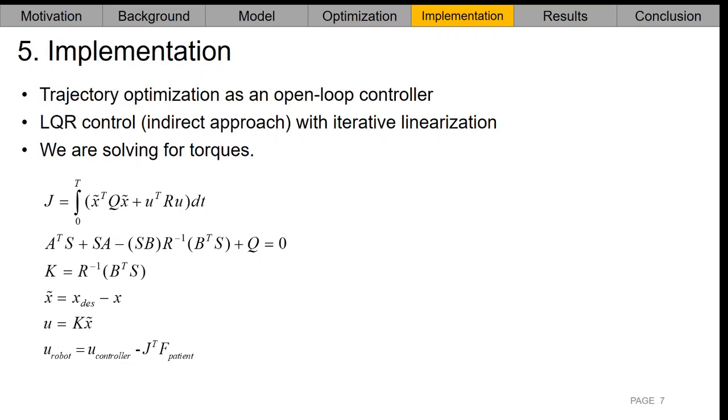Since the gravity is counterbalanced with the plane, there are infinite stable points and linearization around any point in the workspace will be valid. In order to find the LQR input, a Riccati equation needs to be solved at each iteration. Now, we can use two approaches to implement the controller.